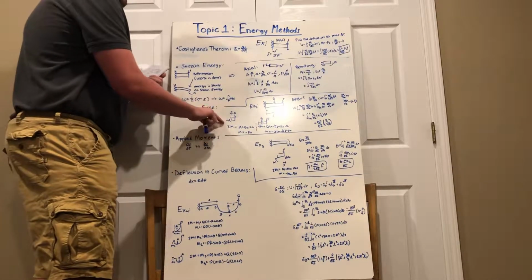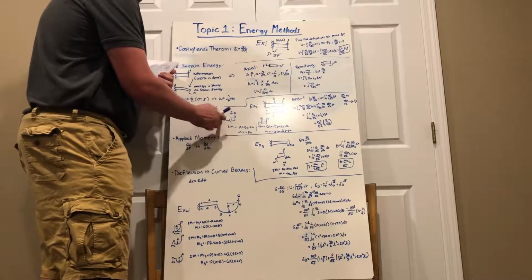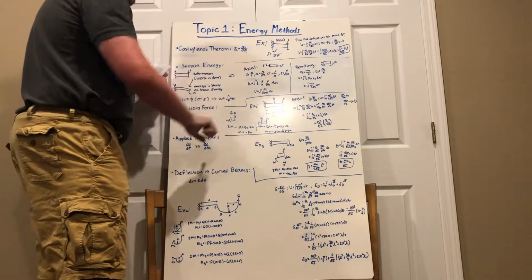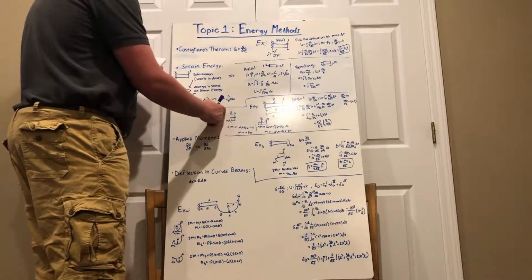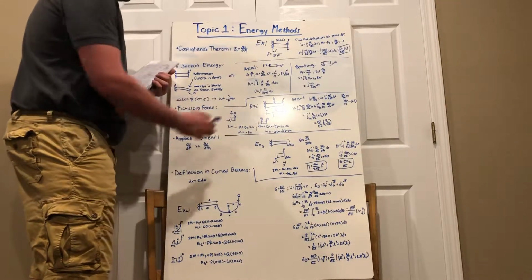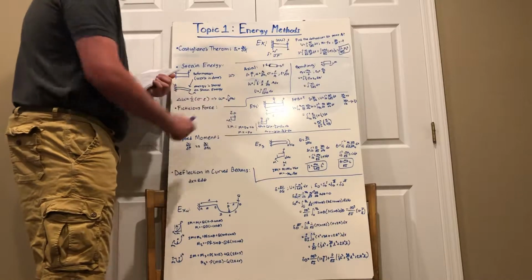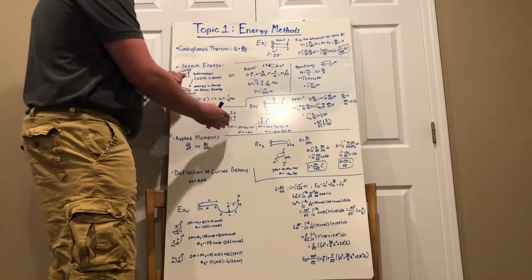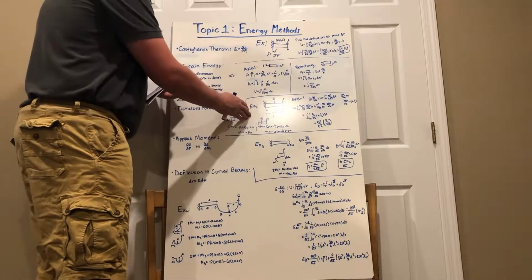So we're going to apply our moment around the cut with our force, and we have our direction. So the sum of moments around this direction in the negative direction is going to be this M plus P times the distance to this cut. We're going to set that equal to 0 since it's not moving. Now let's rearrange this to have M equals negative Px. All right, cool. We have our moment equation for this first side. Now let's keep that in mind and move on to this next side.